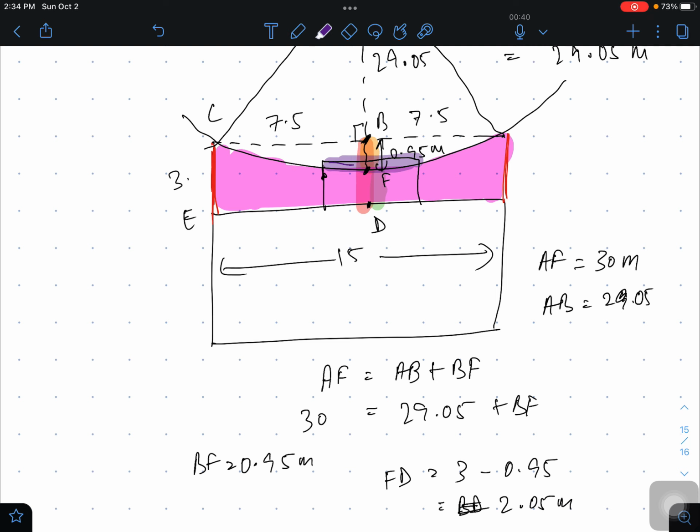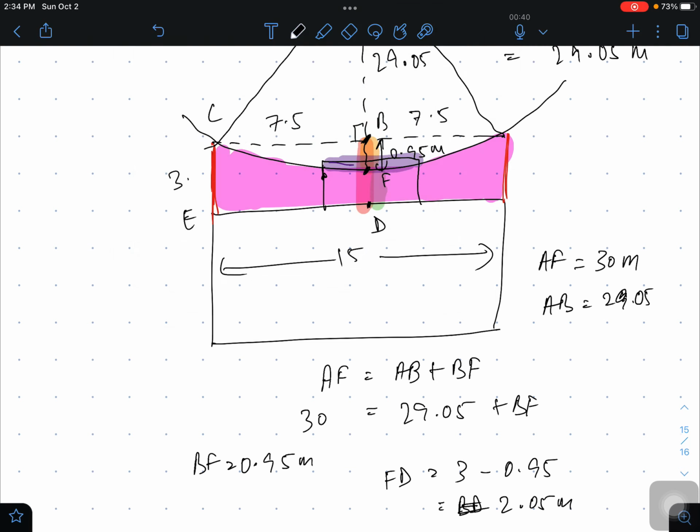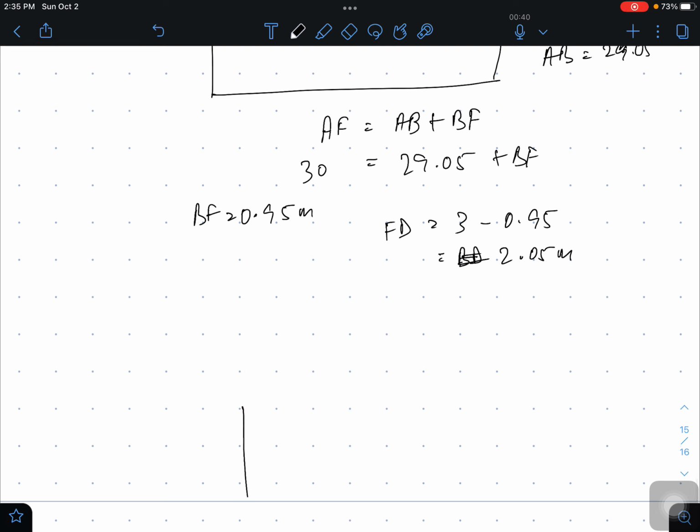What we can do, again as we saw previously in the protection zone, you can increase the height of this 3 meter rod without increasing the copper length. You can place it on the parapet walls. If there is a parapet wall here, you can increase the height of the 3 meter rod by 1 meter or 1.2 based on the height of the parapet.